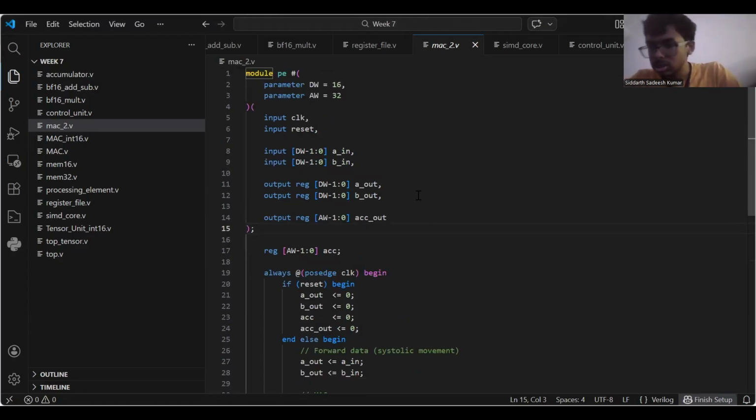There are two approaches to designing a MAC. One is using a systolic array, because the main critical issue with matrix multiplication is getting the inputs. You get an array of inputs and you have to arrange it in a matrix and then load it to do matrix multiplication. You can't do anything else other than that. So we either get a systolic array based input, structure it, and do MAC operations based upon that. Using that, we can get more of a dot product, which is not ideal for an AI application point of view. It's more towards an AI accelerator, hardware accelerator point of view.